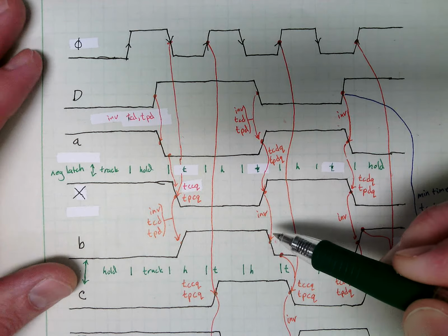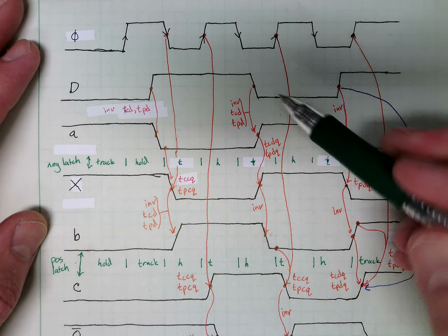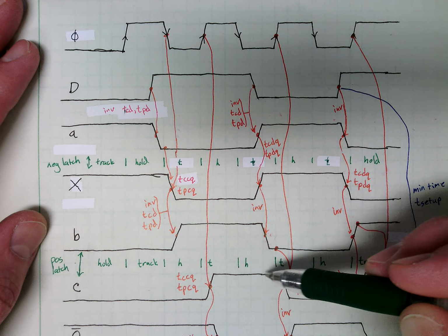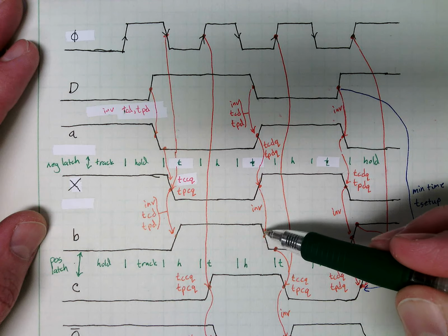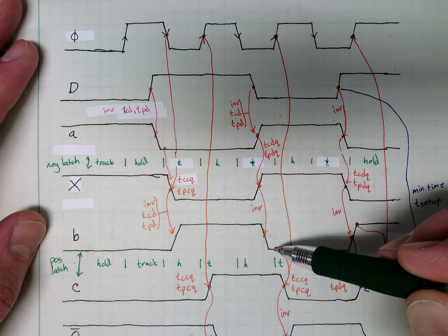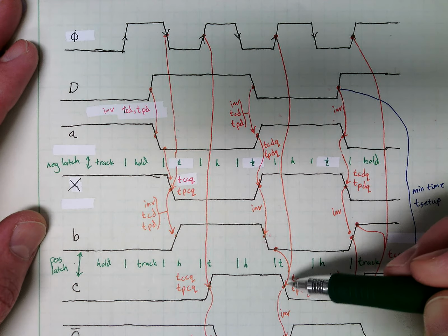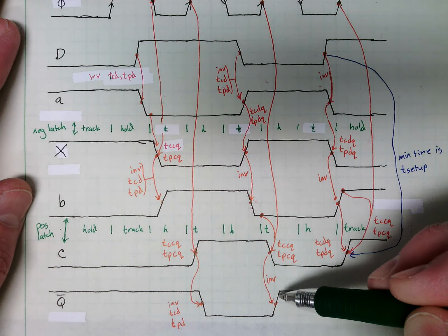get to node B. As soon as our clock rises, our second positive latch was in hold mode, so nothing was changing on the output. You see that right here. Then we go clock to Q delay. Our B changed. Our B was done changing before the clock event happened. Clock event happened. That's this clock event here. Everything's on a grid. And then we go from clock to Q. That's the delay for that latch. Of course, an inverter to get to our Q bar.